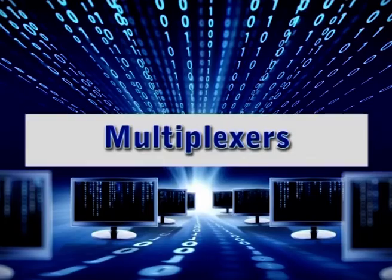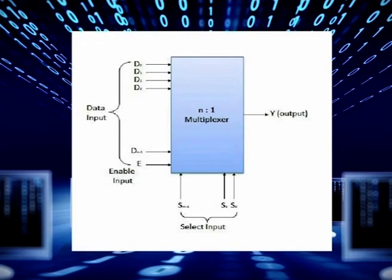Our next topic of discussion is a very important topic called multiplexers. Multiplexer, which is also called mux, is a special type of combinational circuit. Let us see the block diagram of a generalized multiplexer. There are n data inputs, 1 output and m select inputs. M is equal to log n base 2.